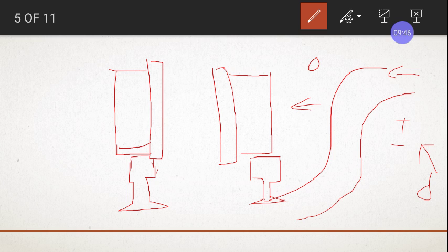What happens when you are trying to move on the curve? The force is applied here like this. So when the train tries to push the wheels, there is wear and tear here. Can you see this side? If this happens and the force is more, then the wheel may get outside of the track, so derailment may occur. So what we do is we try to maintain the wheel inside.